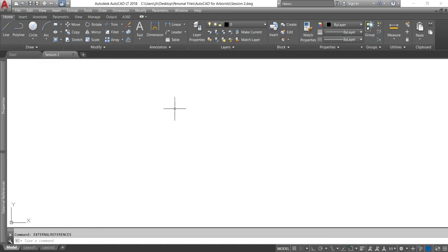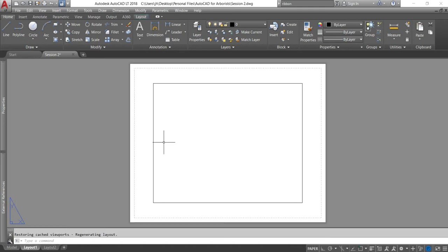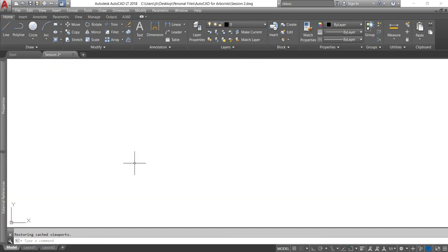So a quick note before we start doing the drawing tools, we're always going to draw in the model space. You also have the layout or paper space. This is where you'll create your printable drawing. If you imagine that this is called a viewport. This is essentially your piece of paper here, and this viewport is a window, if you will, which will show the elements that you have entered in onto your model space. So ensure you're on the model space before we start drawing.